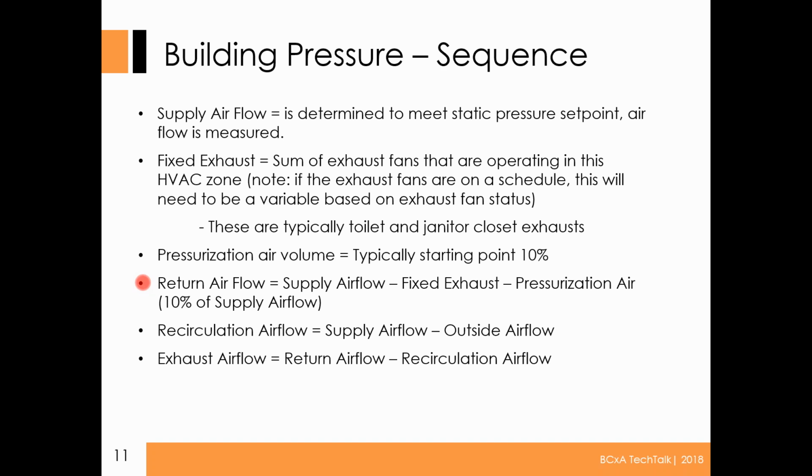Return airflow is going to be that supply minus exhaust minus the pressurization air. This is what often is forgotten in the sequence. Okay, and again, I'm saying about 10% of the supply airflow is that pressurization air. The recirculation airflow is what actually comes back and recircs from return back to supply, and then your exhaust airflow is these values.